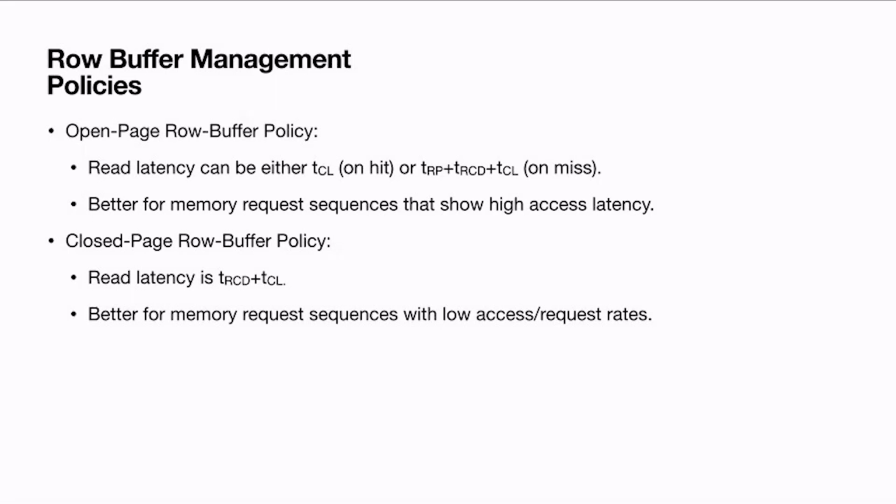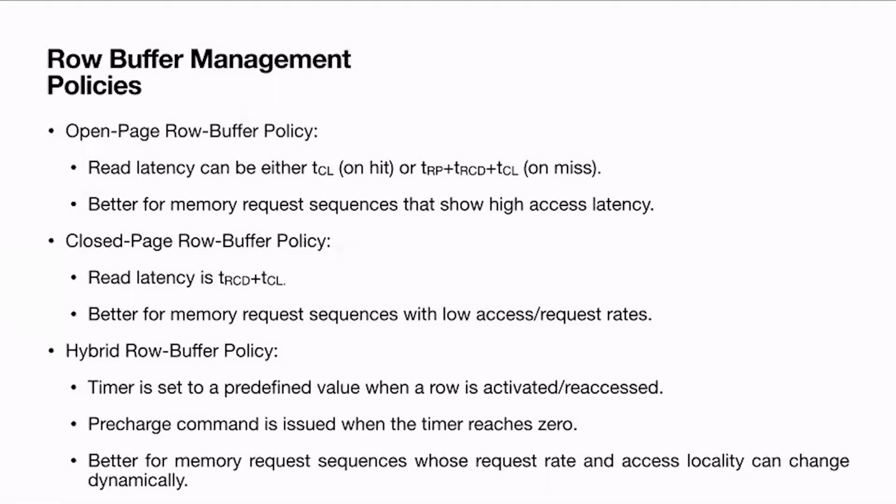So depending on the application characteristics, we can go for the open page policy or the closed page policy, or we can also go for something intermediate to these two. That is called a hybrid policy. We can set some time for this row to be open.